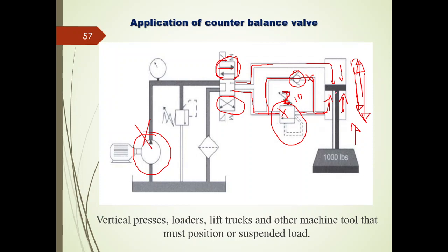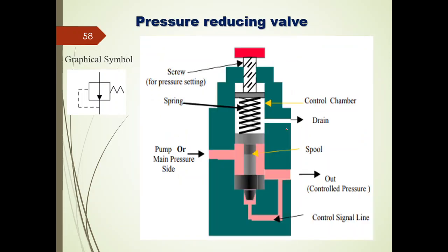But due to this heavy load, which is acting because of gravity, it is not necessary to switch on this pump continuously. That is where we use this counterbalance valve. That is the application. Next one is the pressure reducing valve.